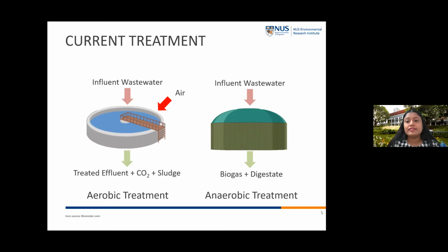And they create sludge. So sludge is the bulk of microorganisms that are growing in the system while treating the wastewater. And to keep the operation stable, we have to frequently discharge the sludge from such systems. So this is about the aerobic treatment.